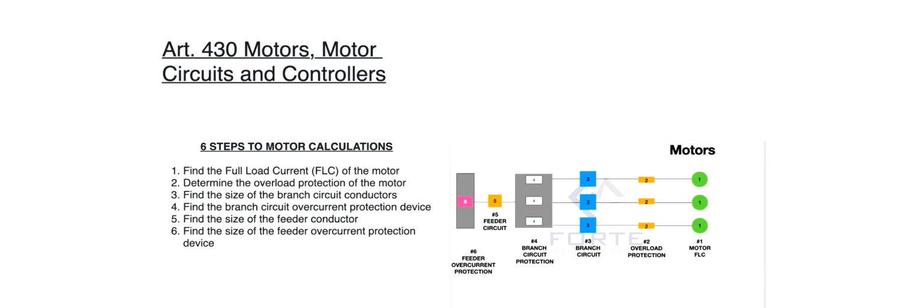back in 430.248, 249, 250, depending. But FLC, when you see that C right there, just trigger your head and just go to the code. When it's FLA, and that's in a future video, FLA is what you use to determine the overload.